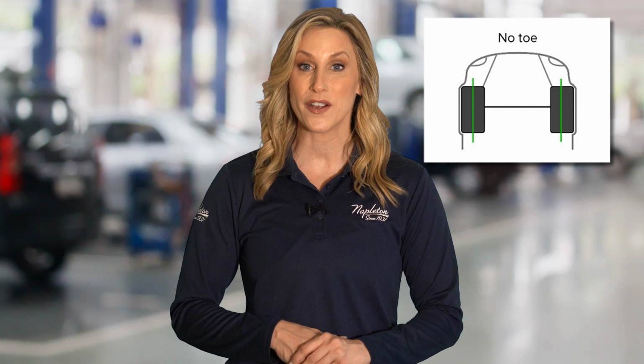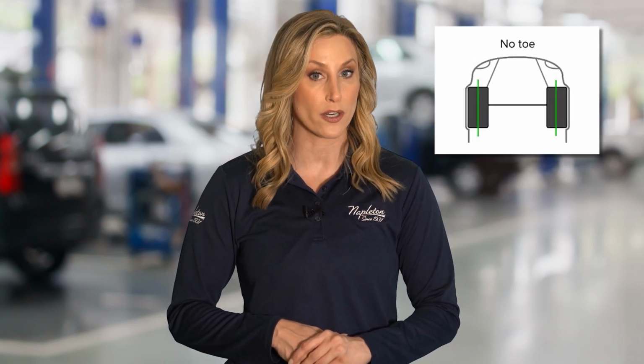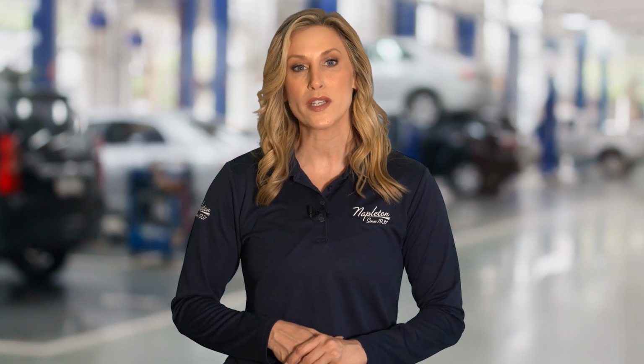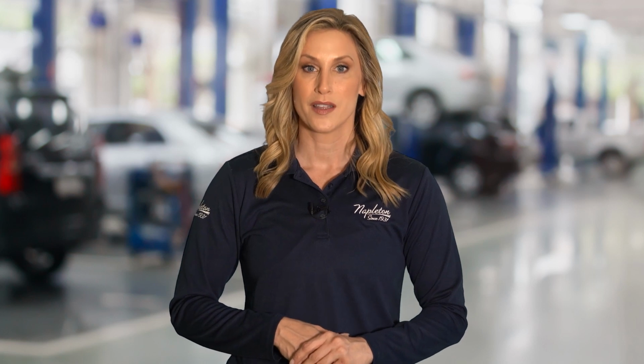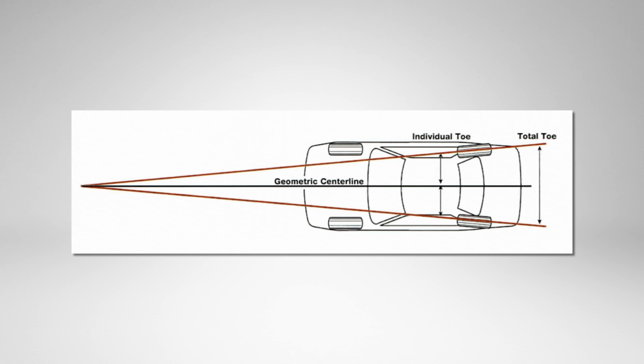Zero toe occurs when the front tires are the same distance apart when measured from front to rear of the tire. Toe can also be described as total toe or individual toe. Individual toe refers to a single wheel compared to the vehicle's center line. Total toe describes the sum of individual toe values. The sum of left toe plus right toe equals total toe. Total toe and individual toe are defined the same when applied to both rear and front wheels of the vehicle.